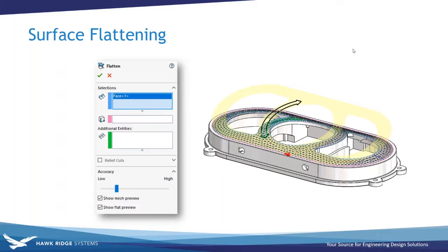The difference is it's not taking into account any material stretch because it's based off a surface. So it's not aware of any material really. It's just flattening the shape. But it will show us a prediction of any distortion in the shape, any deformation in the shape. So it can still be a really useful tool. So let's just show you how it runs here.